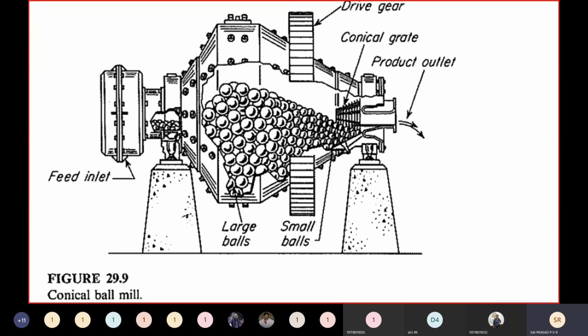The next thing which we have seen is that we can also pour water into the ball mill. What is the main purpose of it? We are supposed to displace the solid particles and bring them to the vicinity of the size reduction zone. Keeping this as a fact, if you pour more water, what will happen? The spherical balls will first strike the surface of the liquid, then they travel in the liquid medium to hit the particle. So there are energy losses. So loading of water is a very important factor in the ball mill.